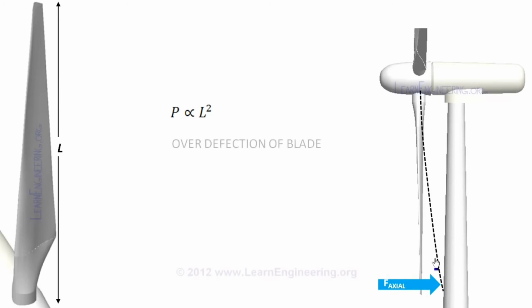With increase in blade length, tip velocity increases. Noise produced by the turbine is a strong function of tip velocity. So, it is not permissible to increase blade length beyond a limit. Another factor which goes against long blades is the requirement of huge mechanical structure, which leads to heavy investment.